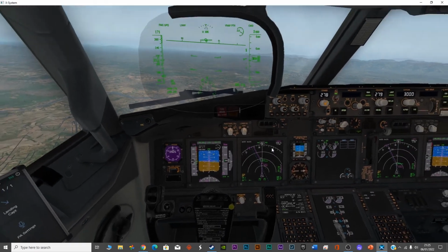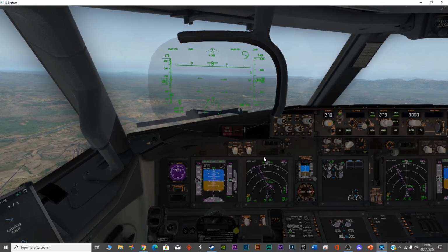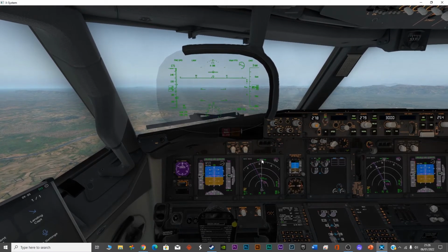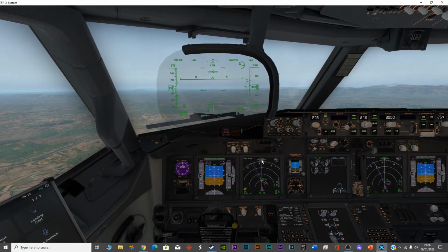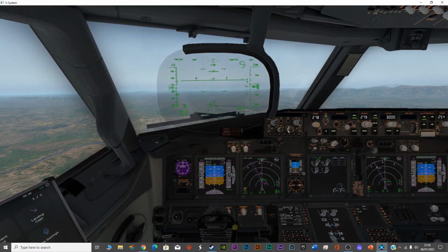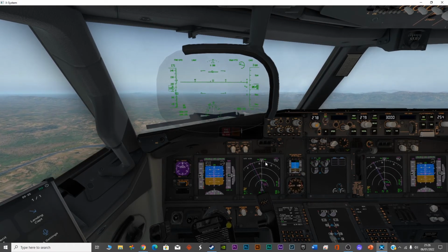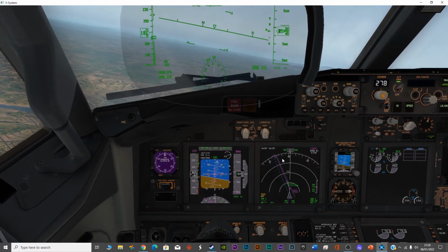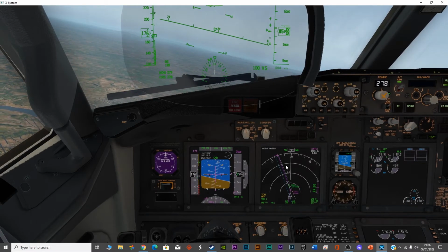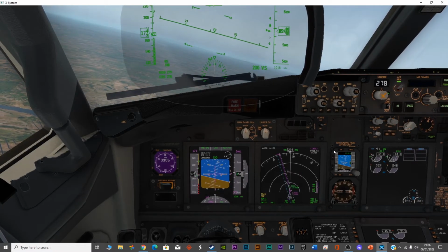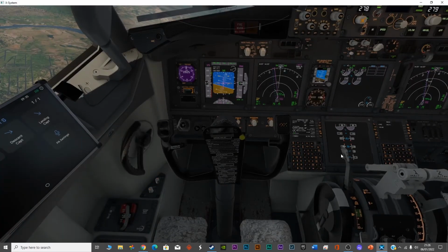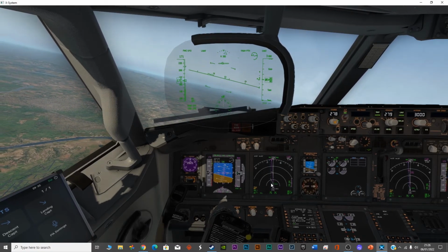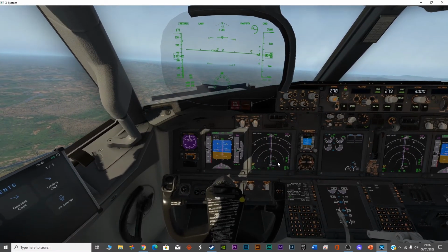Some trick I use, I don't know, maybe you have a different technique, or maybe the pilots do it the other way around or with some other technique, but this is how I do it. Good option. You can easily control the speed. During the descent it's difficult to control the speed because obviously the plane is going down, and then you have to use the air brakes and stuff. So this is a good point. Okay, so after this point the deceleration will again start and the plane will start to descend.